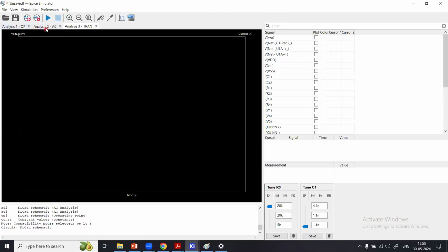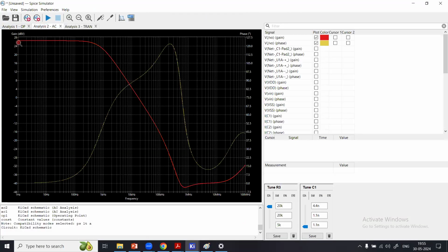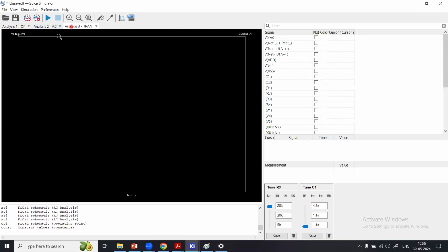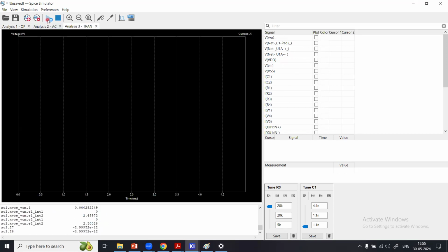As you can recall from the plot, you have a good gain here, about 25, 27 dB, but the cutoff frequency is like 300 hertz. And now the input signal frequency is 1 kilohertz. So obviously your signal will be reduced as compared to input. We would want to verify that if we run that. So let's click run, and it is running the simulation.